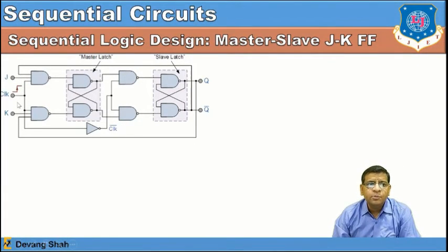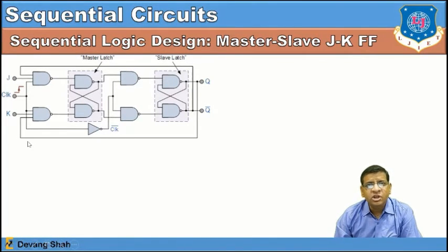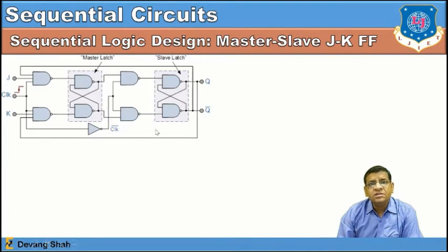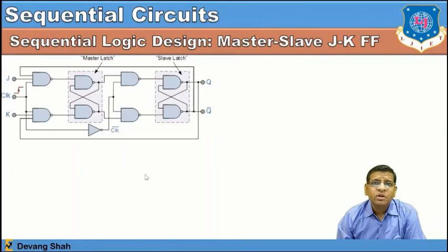So first the positive edge of the clock comes, the master is enabled and changes the data, and after the positive edge, the next stage depends on the negative edge trigger, right? Ultimately this removes the race condition, because the second stage has to wait for the output of the first stage and the negative edge of the clock signal, right?